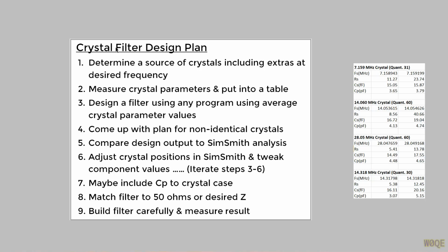And based on what your use of the crystal filter was for, you may not care about the exact frequency. In some cases you do, some cases you don't. But you've got to determine where the crystals are going to come from. Before you design the filter, you need to buy the crystals because you need to measure the parameters.